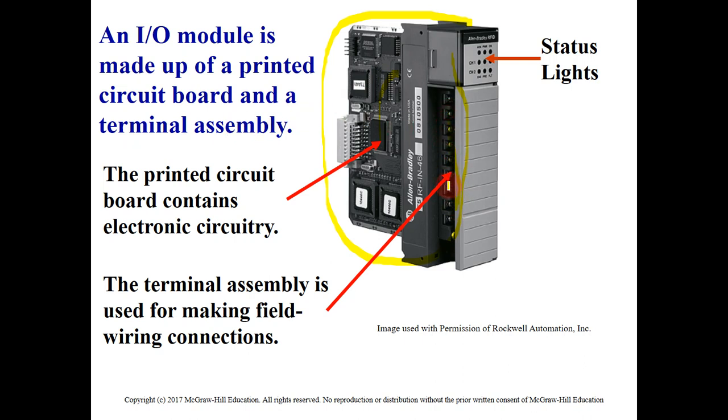In this part of the module, we have the terminals. We need to connect the terminals to the devices. So the sensors in the case of input, the actuators in the case of output, will be connected to these terminals. When these terminals are connected here and fixed, this whole part can be removed. So it will be plug and play.